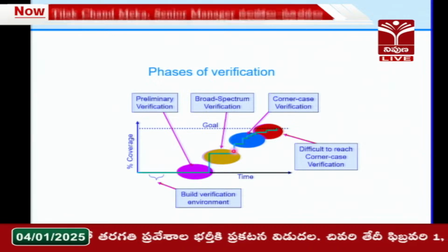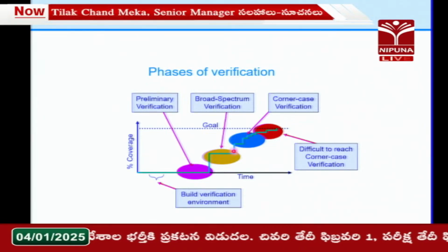First, you build your test bench environment and debug it to ensure it is ready to test the actual RTL design. Then comes broad spectrum verification, where you apply a lot of stimulus onto your RTL design, run it with various stimulus, and ensure that all or the majority of the requirements are met. If after the broad spectrum verification they are still not met, I will go to directed testing, where I do the corner case specific scenarios.